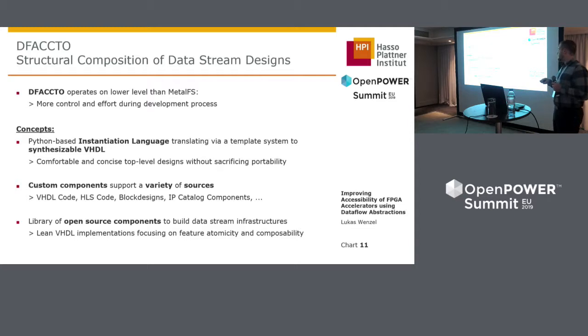The very important part was that we wanted, and this is some kind of contrast to what is usually found in the Vivado IP catalog, where these components are usually defined to be very powerful and complex and have many different application scenarios. We wanted to do just the opposite, having each component do exactly one thing, and that only at the most rudimentary level, and then have a system of composable modules that come together to perhaps create the same effect, but do not need to create the whole feature set that the IP component would have done.